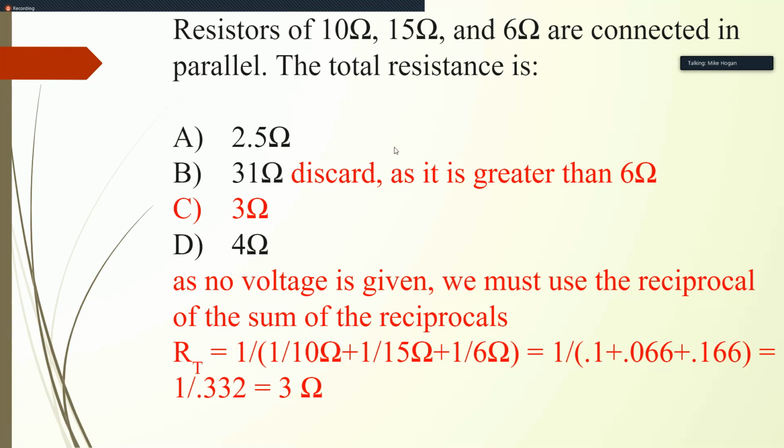Usually what I hear from folks who have taken the test, you're having to calculate parallel. You know, usually it's either they're only giving you one value that is less than the smallest resistor in parallel, so that's a dead giveaway, or they give you typically the same resistors in parallel, which means that you can take that resistance, divide it by the number of resistors to get the equivalent resistance.